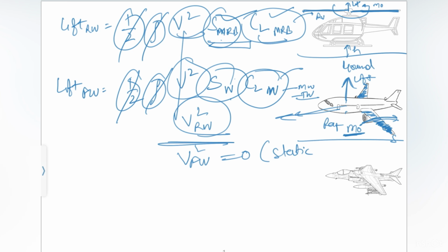In the case of a helicopter, even if it is at one position x and the main rotor blades are rotating, we change the attitude, we increase the CL value, the surface area remains the same, the velocity is the same at which the main rotor blades are rotating, and we generate the lift, and that's how a helicopter can take off and land from any point.